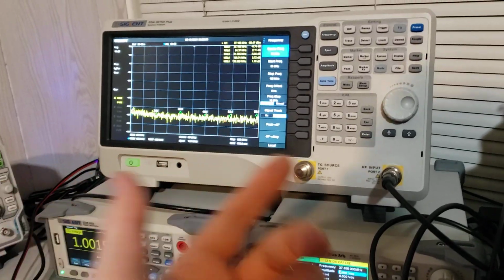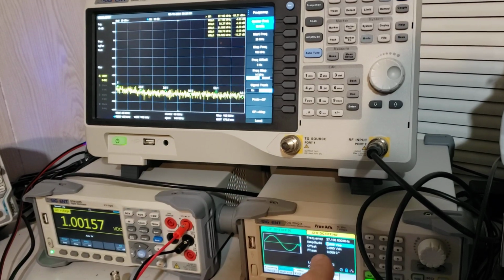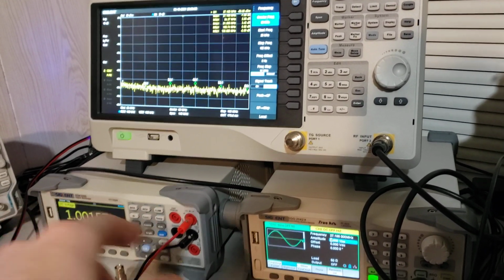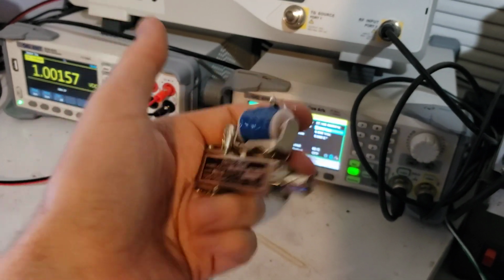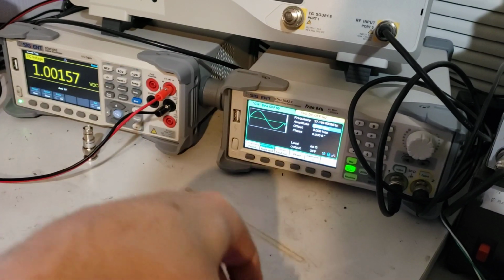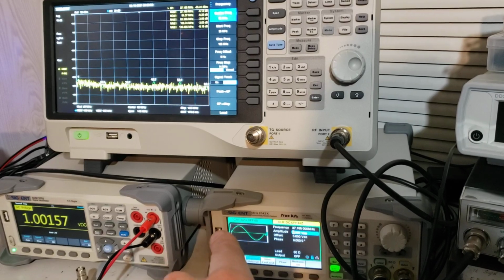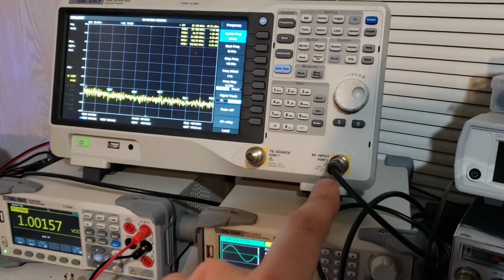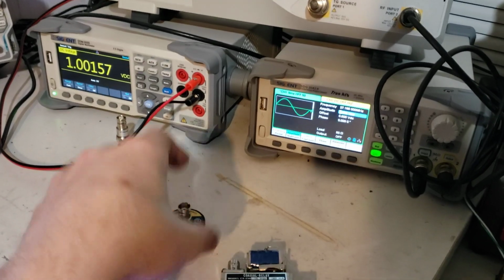I mean, I can measure all of this stuff with one click of a button. So just for example, this only has one input signal, but I want to measure two signals. I want to measure the input to the amplifier and the output from the amplifier. So I can take a relay like this and switch the signal going into my spectrum analyzer. So one moment I'm measuring the input to the amplifier, click over, next moment I'm measuring the output of the amplifier. And I'll do that with a Bird sampler slug, one on the input, one on the output.